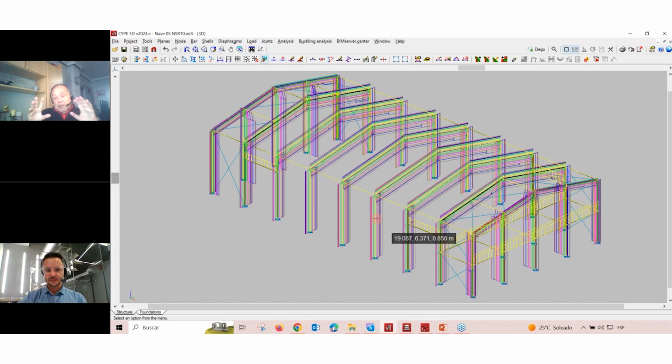By the way, now we are using Photo Frame, and this job is already done. But if you don't want to do that, you can do it on your own. You can start using the same features, introducing loads one by one, and then you can create your panels. And if you introduce the load in those panels, the software asks you in which direction you are going to move those kinds of loads. So this is the way to do it manually.